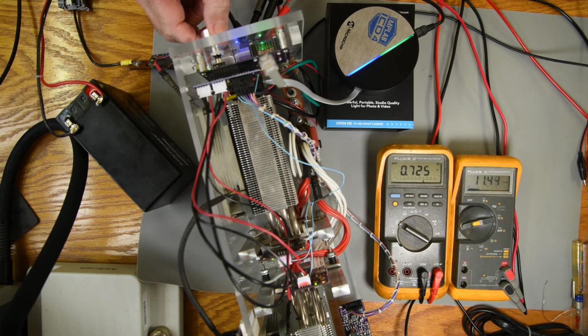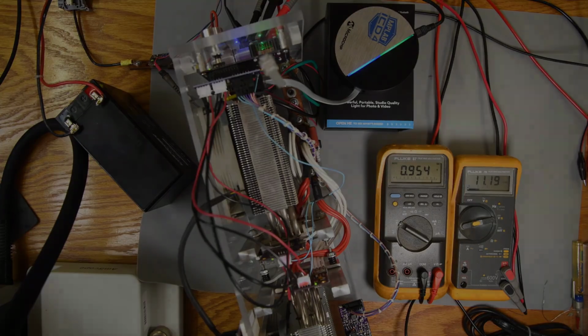If it was the coarse current stepping, I don't think it would get to the half an amp ripple level. The DAC value must be changing by about 20 to give me 0.5 amps of ripple. That's got to be a code problem I need to fix.